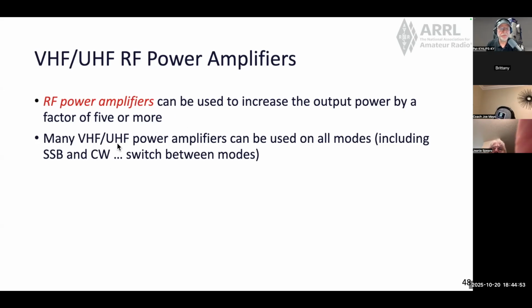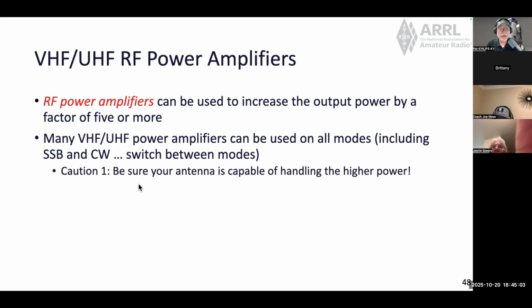Many VHF and UHF power amplifiers can be used on all modes, including single sideband and CW, and you switch between the modes. When you're doing this, if you do an amplifier on your radio rig as you get into this hobby, be sure that you make sure that your antenna is capable of handling high power.